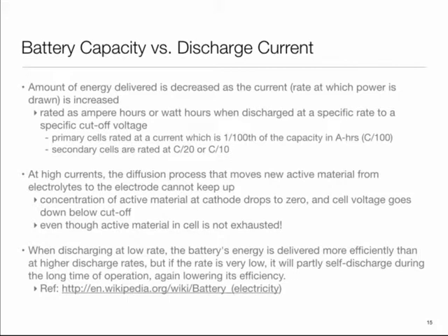Okay, so there are several things at play out here, right? One is that our ability to extract depends upon these two factors. The other is, in case of rechargeable batteries, when we put energy into the battery, we are not going to get all of it out, okay? Because the recharging circuit and all are going to have inefficiencies. And the final part is, if I put the energy in now, and if I wait some time before I extract the energy, I will have a time-dependent loss which will happen, okay? So these are losses in the circuit, so one has to factor that in also in terms of one's strategy.